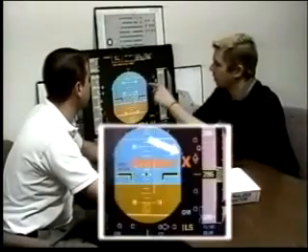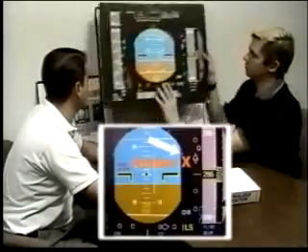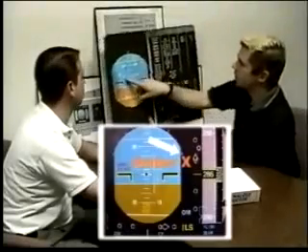How would you degrade from normal law? You could degrade 2 different ways. One is the catchphrase, multiple failures of redundant systems. The other way is by getting into an abnormal attitude configuration. Starting with degrading into alternate law, what would be some specific indications that you're in a degraded flight control law or even alternate law? The easiest way to determine that you're out of normal law is by looking for amber X's that are here. And that looks like this.